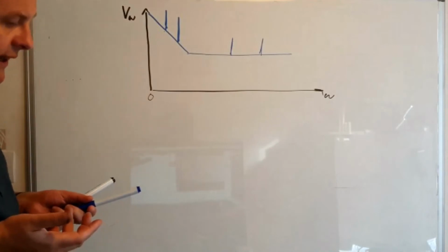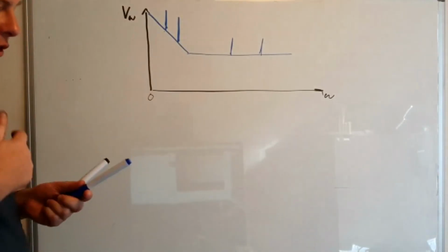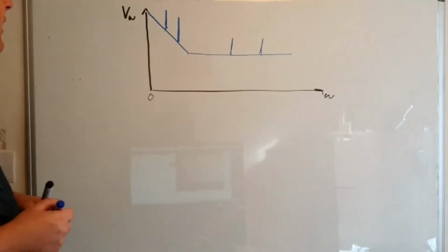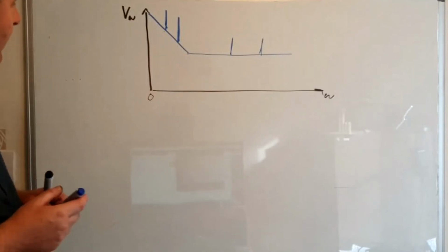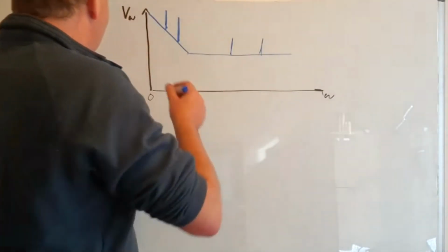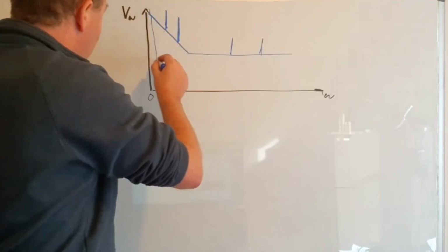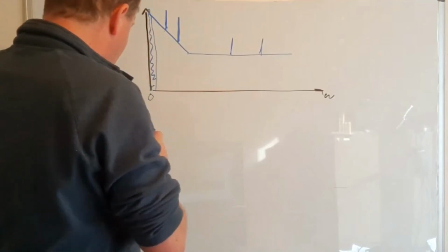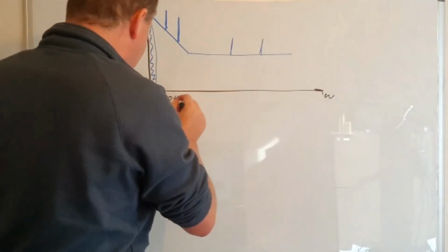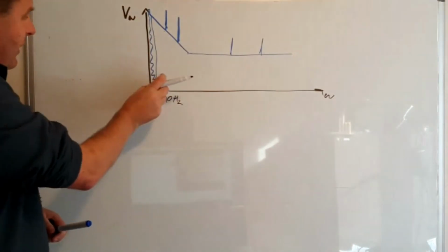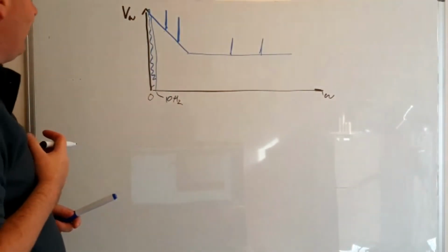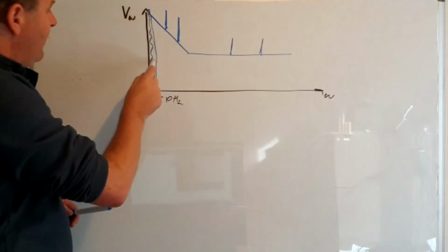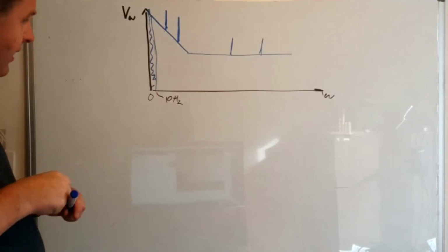So you might say, for example, measure averaging your signal for a certain length of time. Say you averaged for 1/10 of a second, then effectively what you're doing is you're measuring the signals in a region like that, where this would be 10 hertz. So we're measuring with a 10 hertz bandwidth because we're measuring for 0.1 of a second, but because we're measuring a region which has a lot of noise, we're picking up this much signal that we weren't interested in. And so we have quite a noisy background.